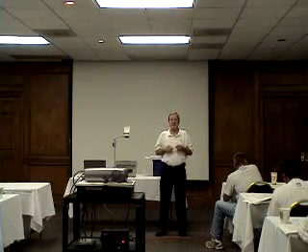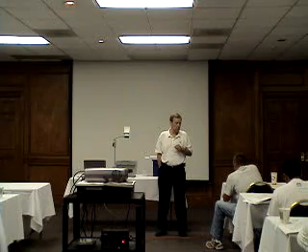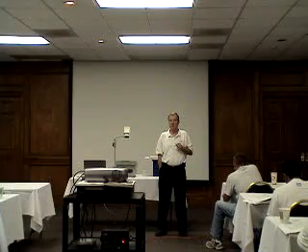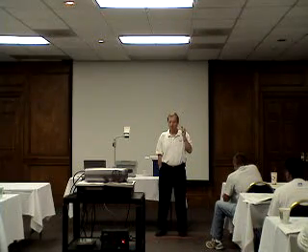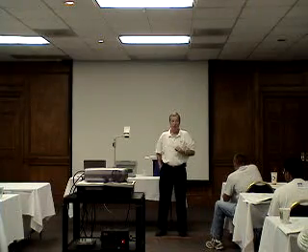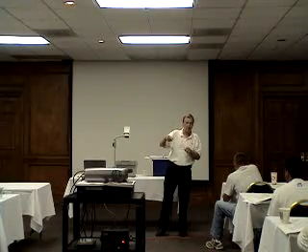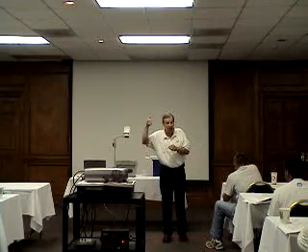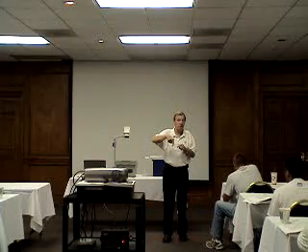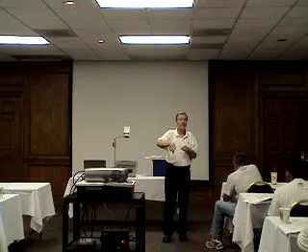On the high side, if my target's 4, I'd have to have a voids of what or higher? 2.5 more is 6.5, because it's got to be more than 2.5, it says. So it would have to be, let's say, 6.6 or higher. And on the bottom side, 1.4 or lower, because it's got to be more than 2.5 on that side.